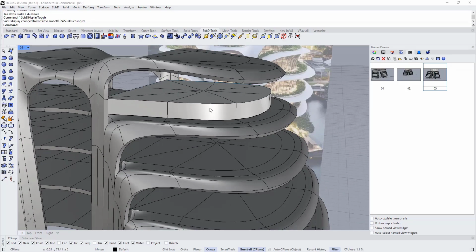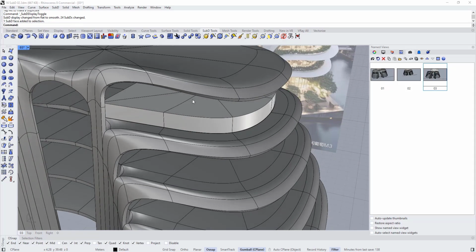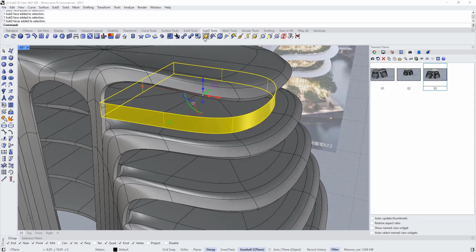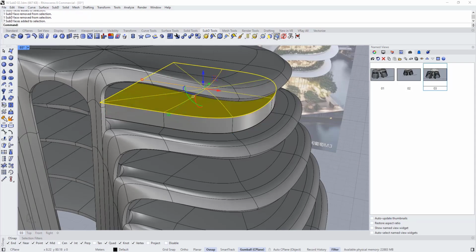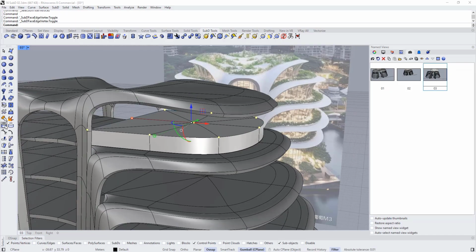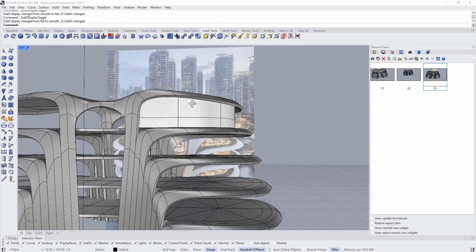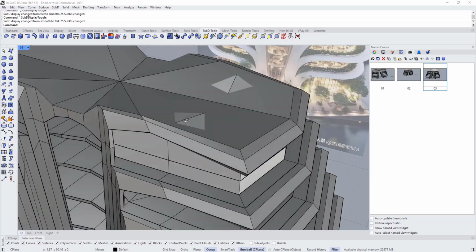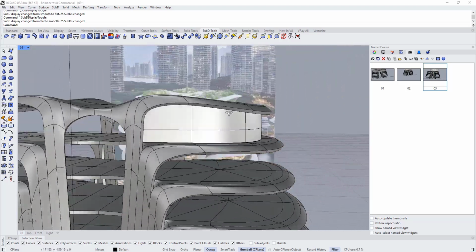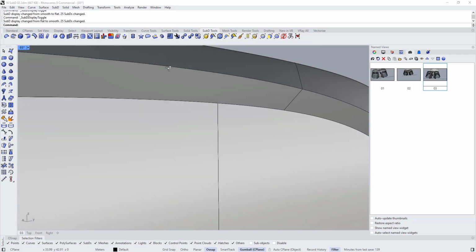And if we want to make these points projected here, we can double click here and choose select face boundary, select the top face, click, let's switch the selection to the points and choose project from here, select the SubD, let's disable this one, select the SubD, right click. As you can see, all the points have been projected to this face. So it's closed perfectly. Maybe not so perfectly, but they are closed anyway, as you can see here.